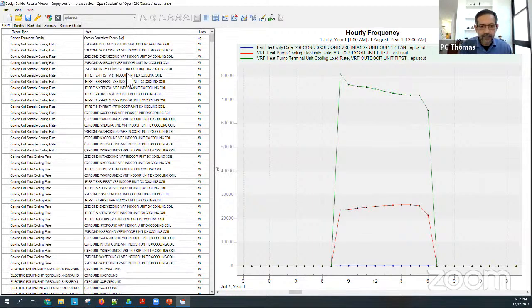Okay. Now, that's a very fast fly through, and I'm sorry we don't really have the time to do much more than that, but I'd like you all to go back, take a simple shoebox model, don't make it very complicated, just 1 or 2 zones maximum. Work through the VRF part, okay? Make sure it's working correctly. Try something. Put better glazing, more insulation, some shading. Look at both the load changes and the energy changes, and then try to say, well, why is it doing that? Is it working correctly? Is it not working correctly? Okay.